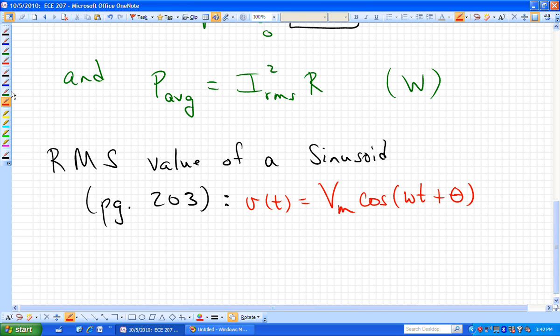From omega, we can actually find the period, which is sort of an aside, so I'll do that in blue. You'll know that, correct? The period, I always remember this relationship. Omega is 2 pi f, where f is in hertz, or cycles per second, and that's equal to 2 pi over T. Meaning, if you wanted to sketch this v of t, and you're given omega, if omega is 50, you can say, okay, what's my time axis look like?